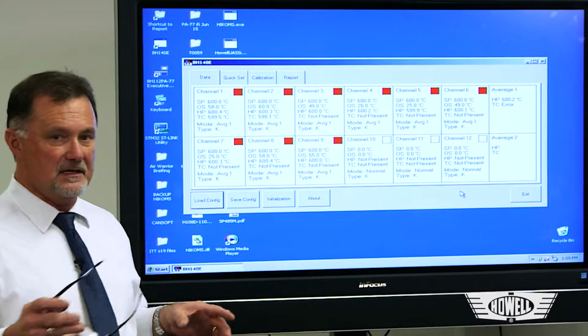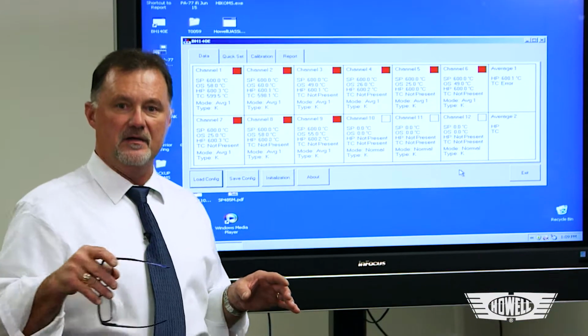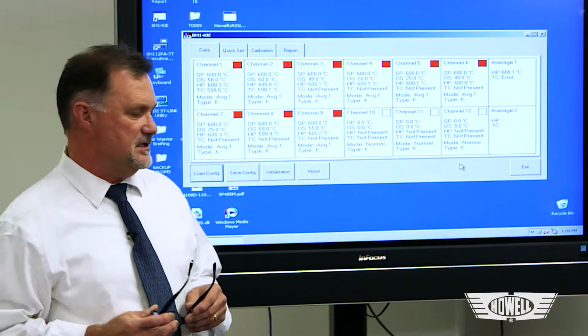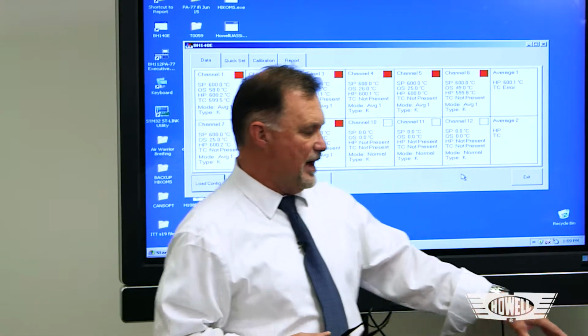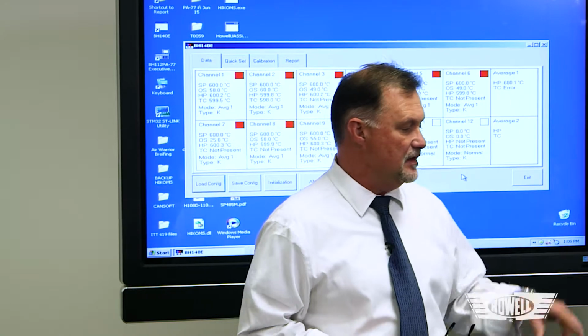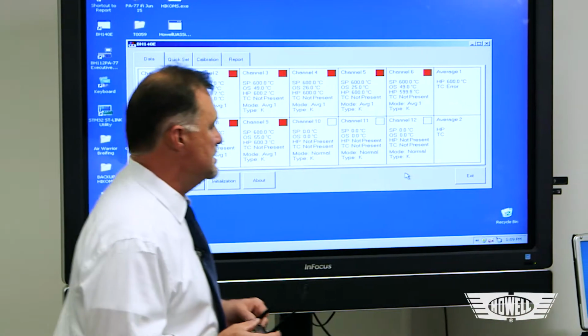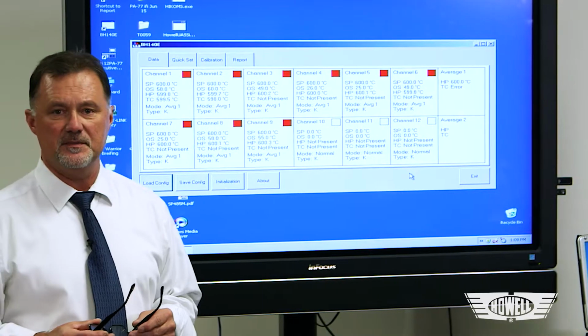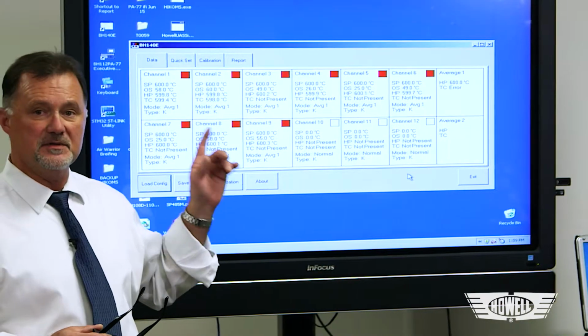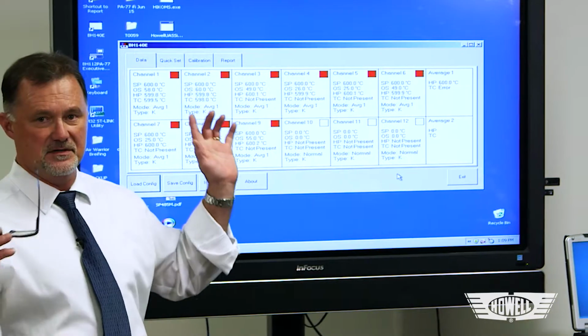So as I've just explained, we are sitting here with 9 thermocouples all at 600 degrees Celsius, which are being averaged. The reality is, inside an engine, there's a disparity of the temperature, and you saw that in Dean's presentation earlier. So one heater probe might be 5 or 6 degrees different than the other. It doesn't really matter. You have an average, which is exactly how the engine works. So currently, 9 good thermocouples, all at 600 degrees, output 600 degrees.